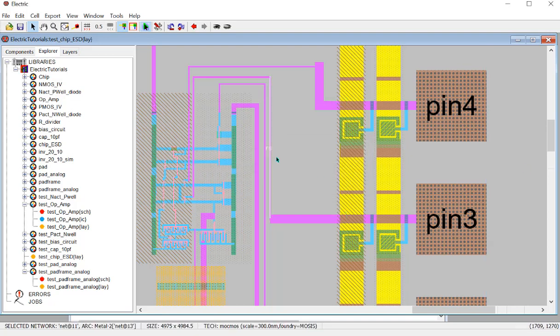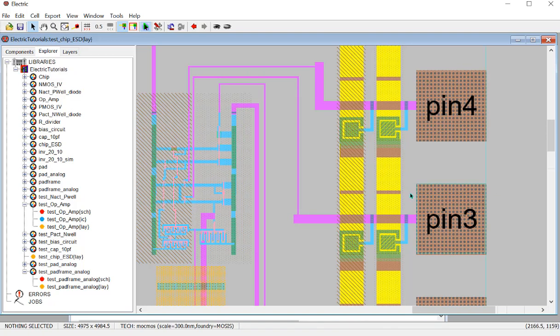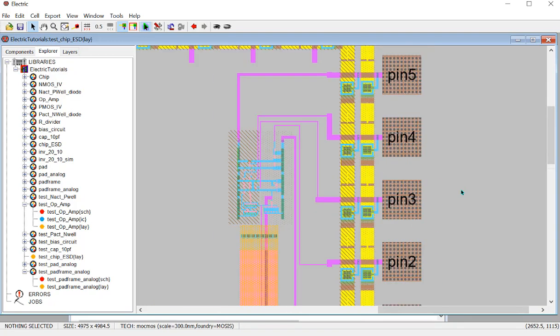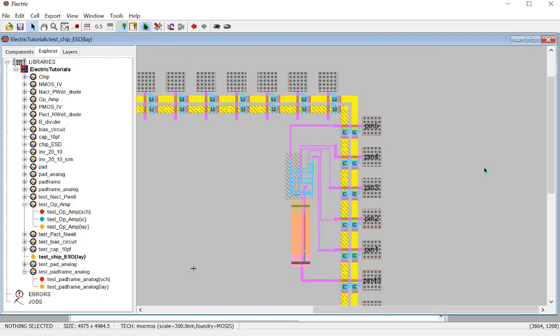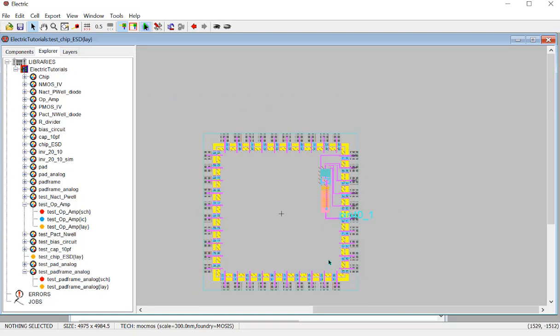So now let's redo this wire. This wire looks bad. Let's pick up this wire, delete it. This port, delete it. Put it here, connect. All right, so this is a lot better. And save, I5 is DRC clean. So we have our first op-amp connected, all these pins. Okay, and inverter. So we want to do the inverter as well.